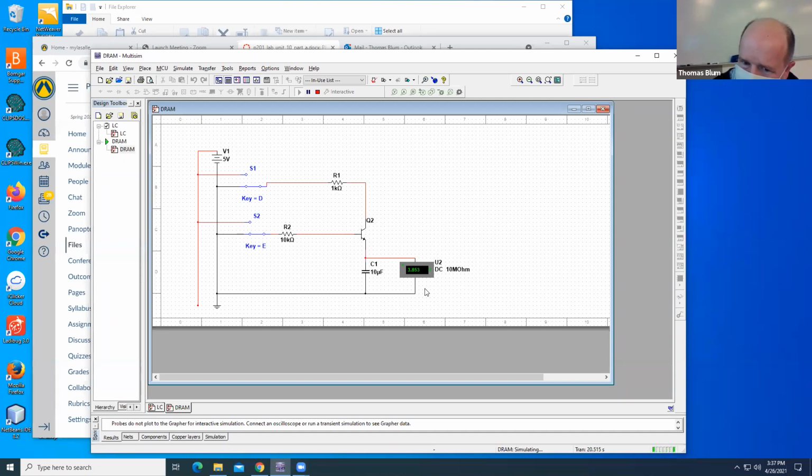Say, for instance, here, this voltmeter has a resistance. And so there's some high resistance stuff that's not infinite resistance. So there's still a time constant. There's still a changing voltage. In this case, this capacitor is discharging, and we would say that it is leaking. It's supposed to be holding its charge, but it's not quite holding its charge. It's leaking some of the charge.